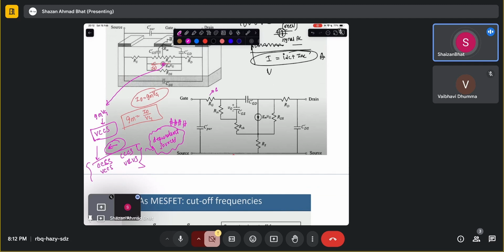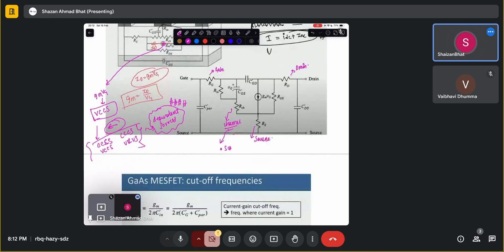This comes because of the gate resistance, which we talked about. This comes again because of the drain resistance, because of contacts, and the source resistance, again because of contacts. This is the channel resistance. This is always going to happen because electrons scatter, and there will be some resistance to the electron motion, and as a result there will be resistance in the channel. This is the drain to source capacitance. Again, there will be delays because of those capacitances, which are charge storing elements.